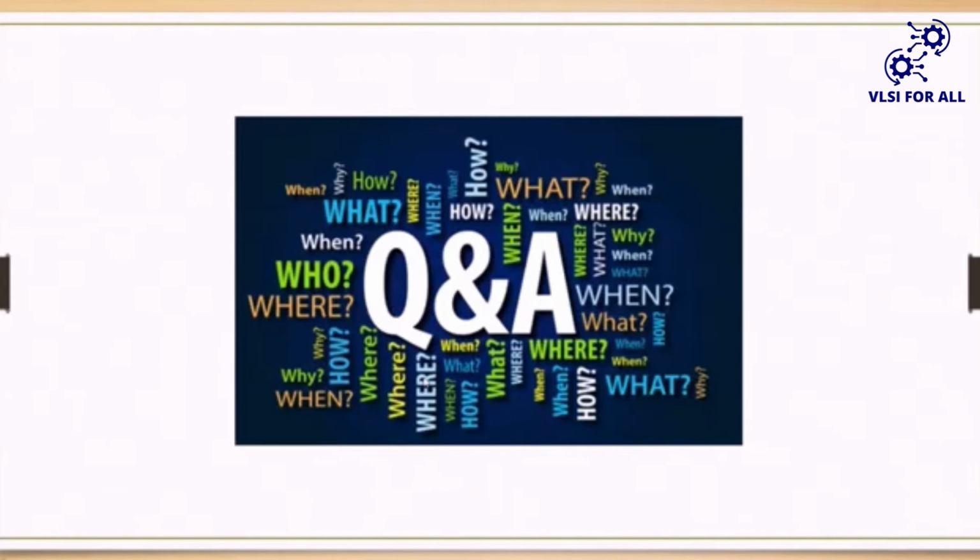You just bow to the synthesis people and give the file back to them. That's it. You can't do anything. You cannot perform PNR. If you perform it also, it is a waste of time. See, if zero wire load model timing analysis itself is not clean, and again you are introducing the wire delays, then how will you get it clean? Tell me.